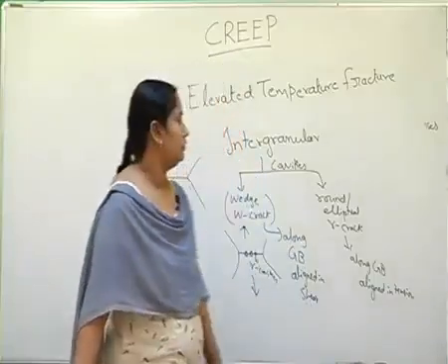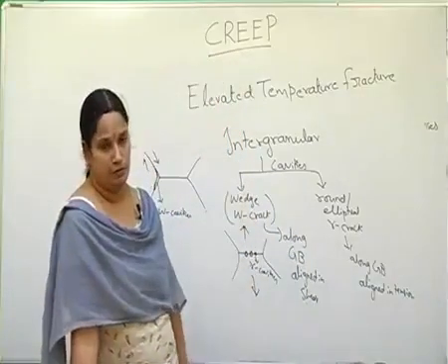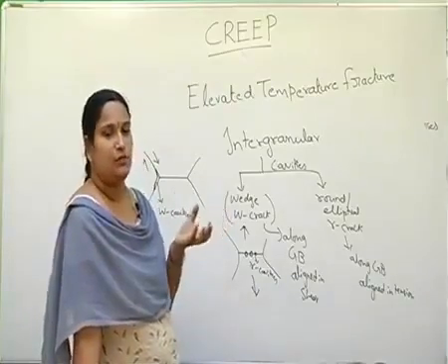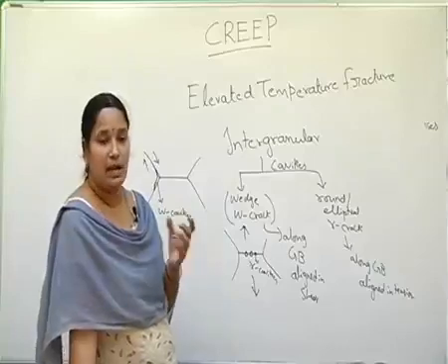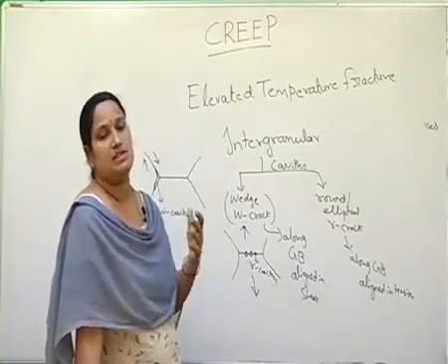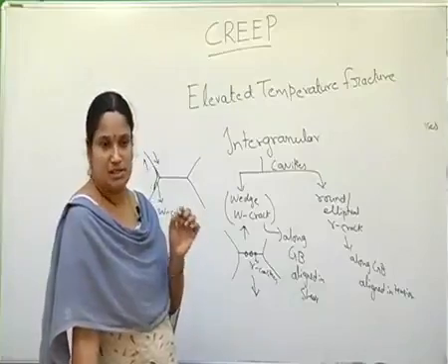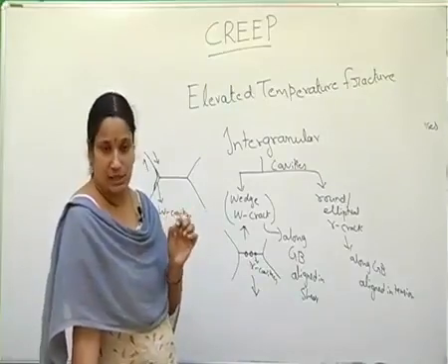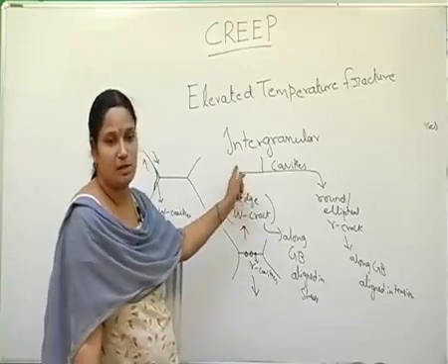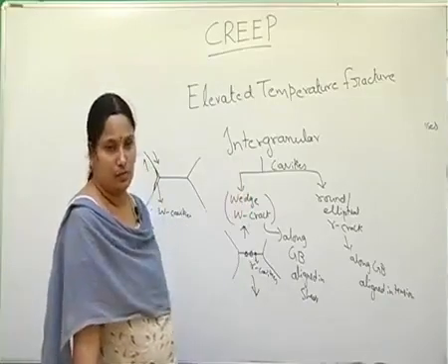In the case of intergranular fracture, the grains in the vicinity of the fracture appear equiaxed, even after considerable plastic deformation. It indicates recrystallization has taken place in the case of intergranular fracture mode.